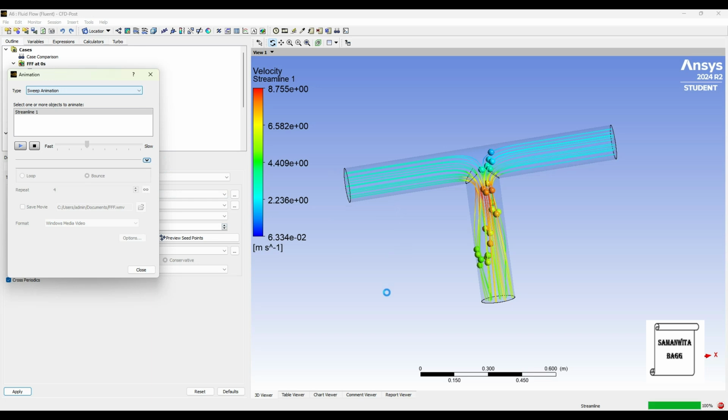In the previous analysis that we had done, this was the inlet and these two were the outlets. So water was entering from here and branching into the two pipes. Here you can see water is entering from the two pipes and it is moving into one and flowing out. Now you can observe that the velocity of one of the pipe was more than the other one. So this speed is more, as you can see, as compared to this one. This was around 3.2 and this was 2.6. So because of the two variation, you can see the variation of speed also of the flow.